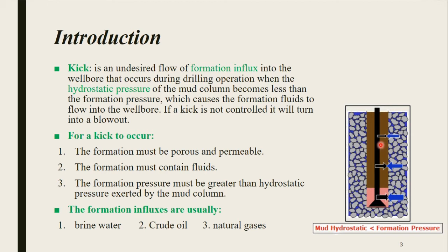In any case where the hydrostatic pressure fails to restrain the formation influx, then the formation fluids will find their way into the wellbore. And this intrusion of formation fluids, or formation influx, is called a kick. So far we know that the formation influx is the fluid inside the formation, any type of fluid, and the hydrostatic pressure is the pressure exerted by the mud column and its density, and a kick is the intrusion of formation influx into the wellbore.